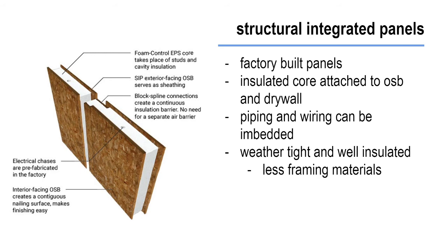And the advantage is that they do not include the number of interior framing members that frame construction does. So they do a better job of thermal insulation, and they have a more weather-tight building envelope. And there's also really no waste created at the job site, and the construction is faster. We don't see them used very heavily in commercial construction, but buildings that tend to have a more stucco or concrete based exterior a lot of times are done using SIPs.